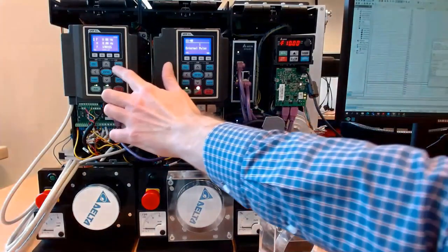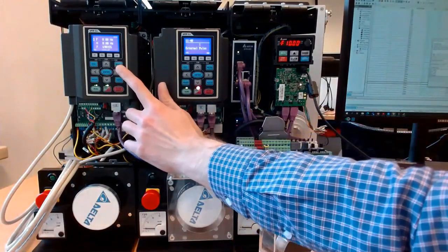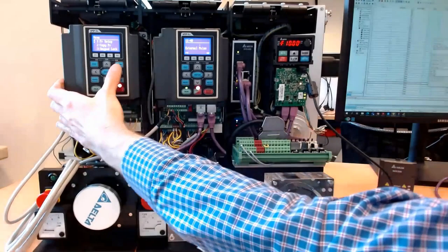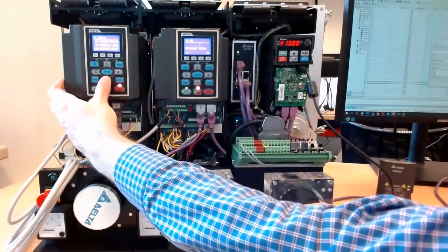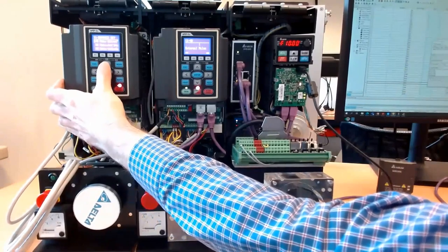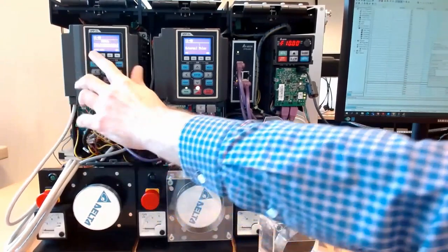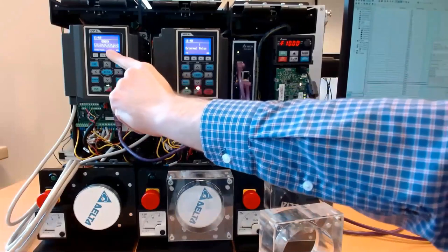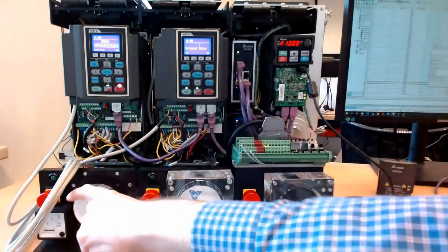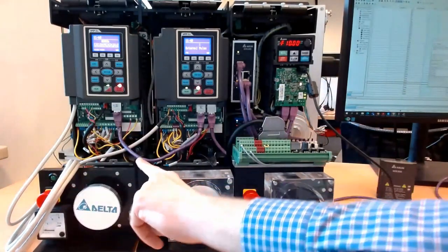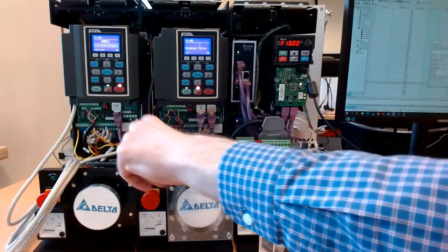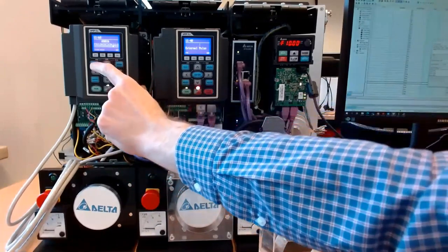So in order to do a homing, firstly, I need to disable this. You need to check which homing method you want to use. You can do that in parameter 1168. Currently, this follows the DS402 standard. So homing number 8 means that the drive will just set the current position as the home position. But you can also do the homing based on negative limit, positive limit, or origin. I will just leave this at its current value at the moment.